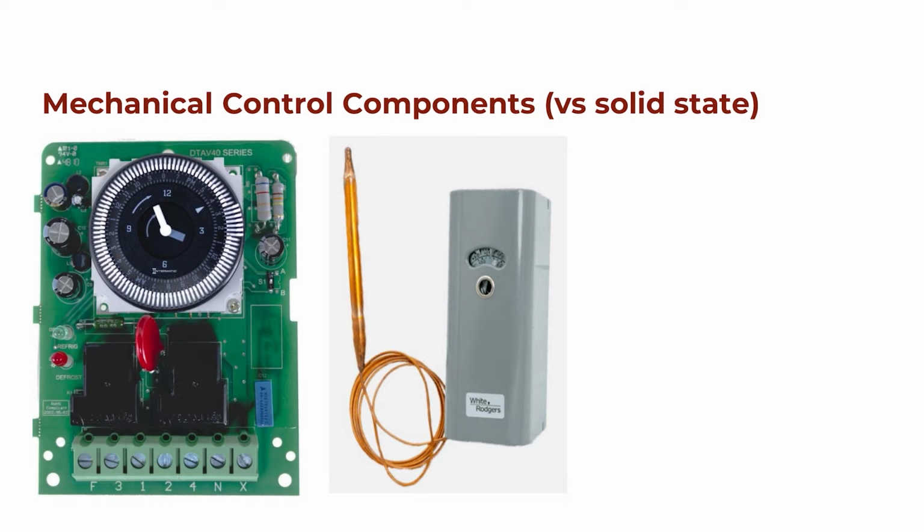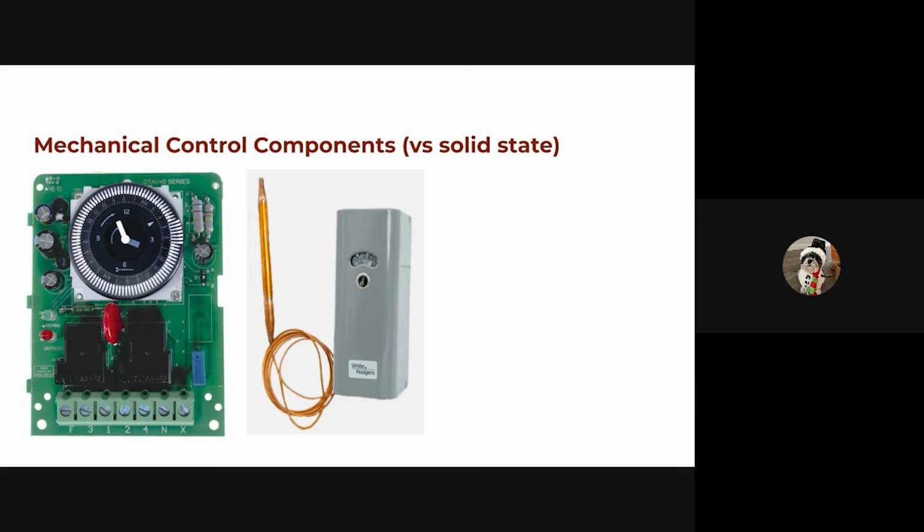The compressors in a supermarket are responsible for pushing refrigerant throughout an entire store that will serve cases that are in various states of defrost or cooling. Right? We're not controlling the compressors locally at the case level.